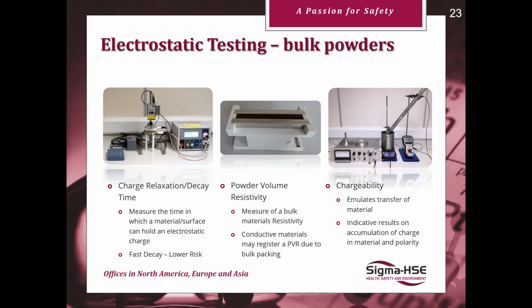So there are various tests for exploring electrostatic properties. These three we have here are for looking at bulk powder materials. On the left-hand side, we have the charge relaxation or decay time test. So if we know we have an insulating material that can generate a charge through movement or otherwise, how long does it take that material to give up its charge and become neutral?